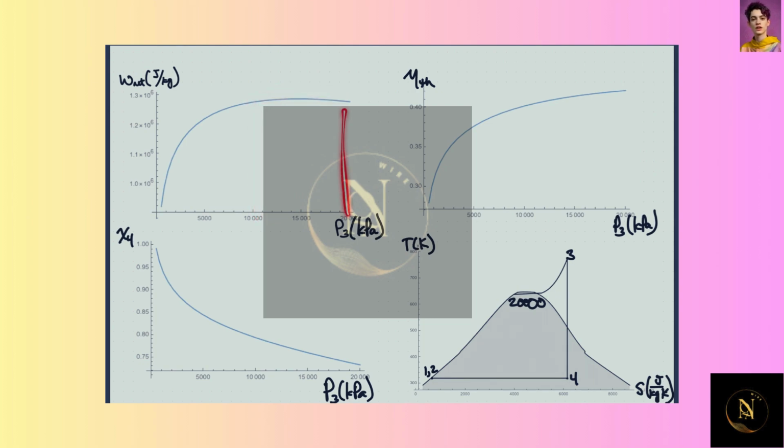And out here at 20 megapascals, you have to worry about leaks and a lot of other things at these high pressures. The efficiencies continue to go up, but we get less return on increasing the pressure. There's some slight rise in efficiency after about 10 megapascals, but not nearly as much. We don't want to be operating at a boiler pressure below 1 megapascal. It just doesn't make any sense.